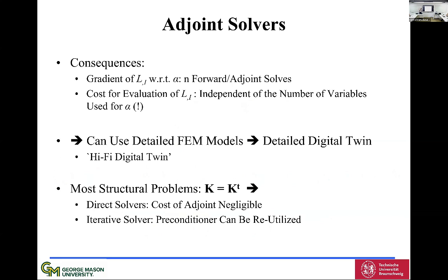We on purpose don't want to use a simple finite element model because I really want to detect where the weakening has occurred. If I take a global model, that's just going to bump over the details. The other thing is that my bridge is not going to fall overnight. So if I do this once a year or once every month, if the run takes a night to run, so be it. There's no rush, okay, as long as I get a good result. So we call this the high-fidelity digital twin.